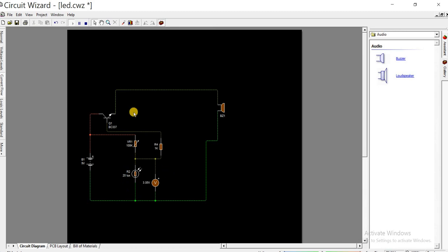So the reason why we use the transistor is to drive a high current device, a high current component like a relay. When we get to hardware programming, we will need to be switching a relay or motor with our microcontroller. So we can't switch it directly with the microcontroller. We need to use something like a transistor to connect to the device. Hope you're getting it.